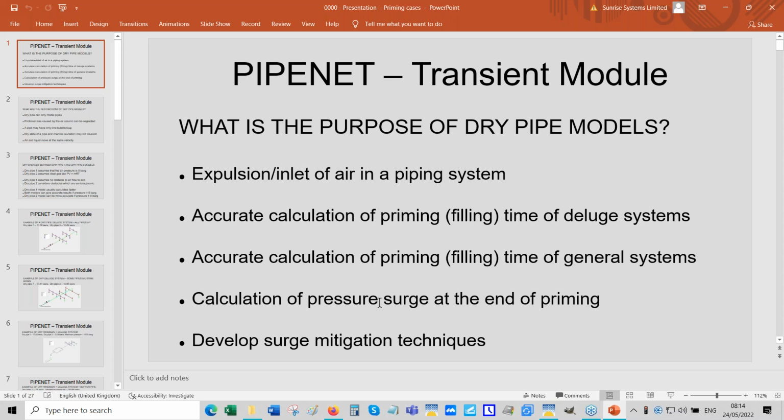But the last nozzle that actually started discharging water is a special one. Why? Because it's much easier for air to escape through a nozzle than for water. And so when the water reaches the last nozzle, there is a sudden deceleration of the whole system.